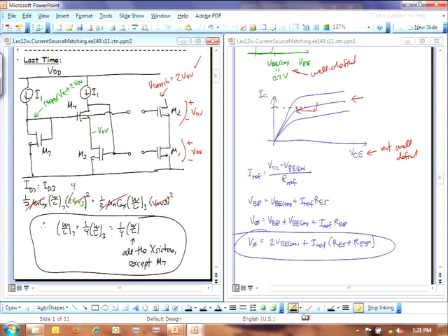Apparently not. The reason why we like this thing right here is because it allows this device M3, which is delivering the V bias out of this, so this is the V bias generator. I can call that V bias 1. I can call this V bias 2. It's delivering V bias 1 to M1, and it now has a VDS across here, VDS3, that's equal to VDS1, which is the transistor I'm trying to use as a current source that I'm biasing up.